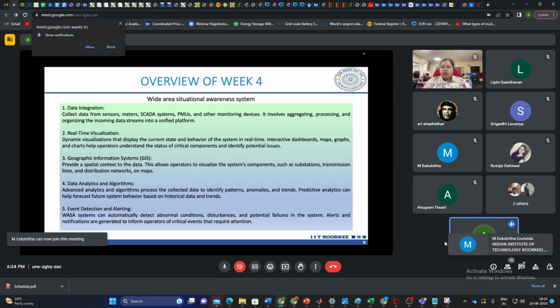They can also use the data of the current state to do some corrective analysis. Let's say at time t equal to t, you know the values of voltages, generation, demand and everything. You may carry out some prediction that at t equal to t plus 1, maybe the system can go to alert state, maybe some unwanted actions will lead to the system moving towards alert state. To avoid that, the system operator will give some control actions at t equal to t to avoid future disruptions to the system.